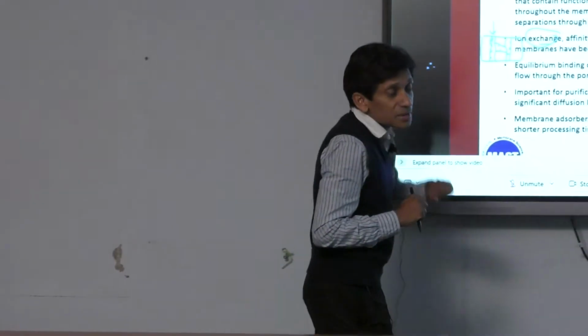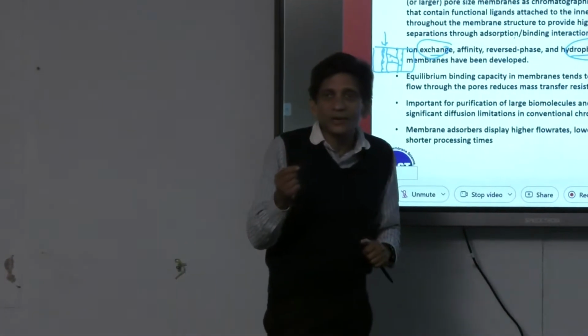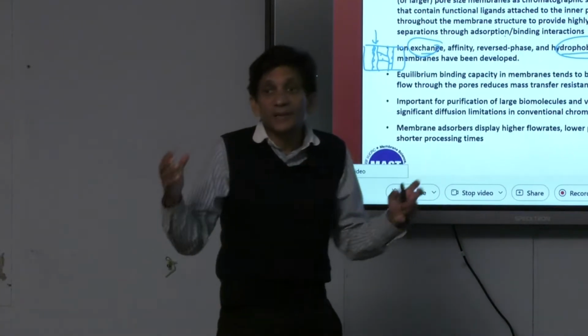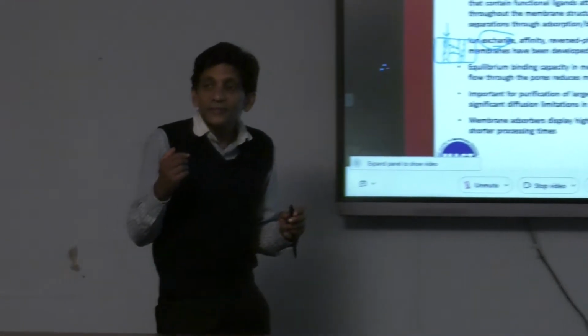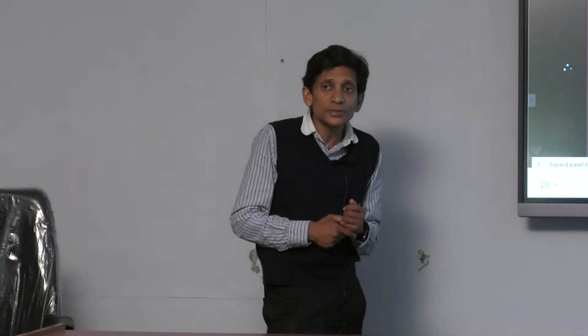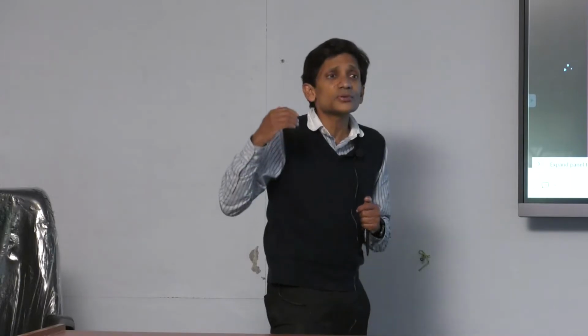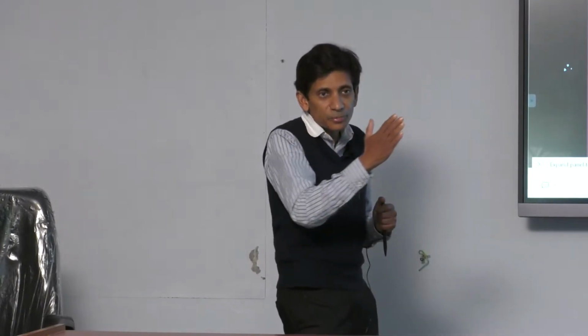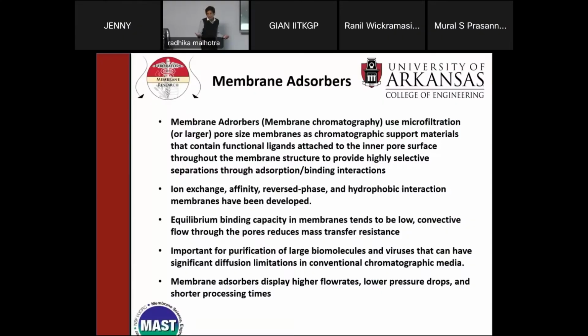But that is very important in the biotech industry because we are not talking about BSA or small species, we're talking about rather large proteins. And they have therefore very low pore diffusion coefficients. So it's very easy to have what's called early breakthrough. In other words, you get breakthrough before you have fully adsorbed everything inside the pores. So you're wasting half of your column. So that's a major disadvantage, and the capacity tends to be lower. That's one of the limitations.